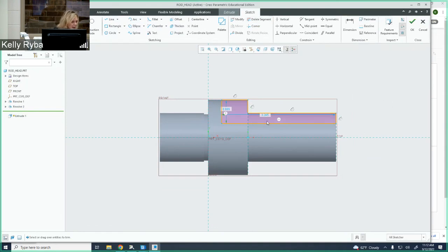Okay, so now let's put this dimension up. This is tied already to the side of the part, and that's why it was giving me the error earlier, and I'm like, what do I want? This is the dimension I want to be 3.06. There we go. And then I need to add a dimension from the bottom to the center line, and I'm going to go like that, and that's 0.5. Now remember, we are not in revolve mode. We are just cutting through here. We're doing an extrude cut, if you would. Okay, an extrude cut.